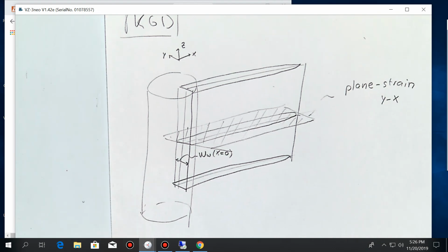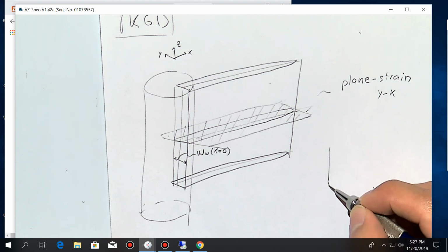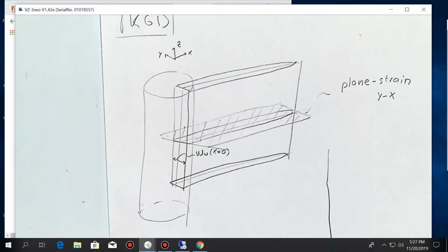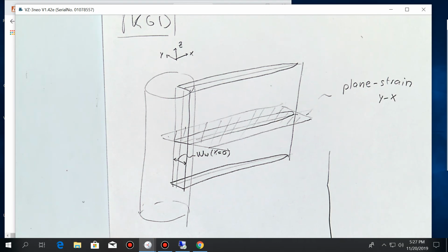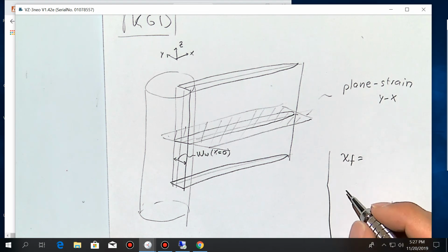And you do again the same assumptions: constant injection rate, Newtonian fluid flow, no leak off, net pressure at the tip of the fracture equal to 0. And you will also find equations that tell you the fracture length as a function of time.